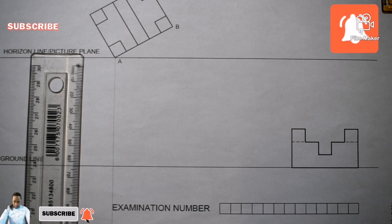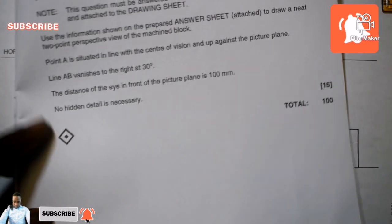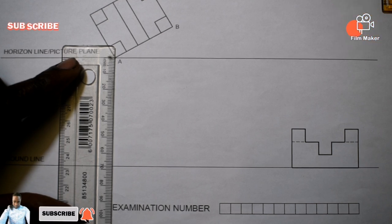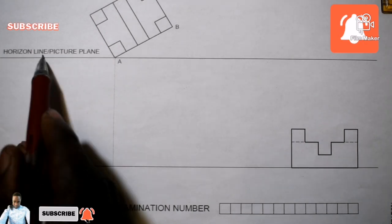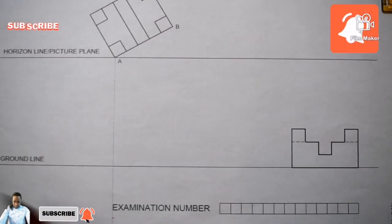The 100 millimeter that they are talking about is this one. The distance of the eye in front of the picture plane is 100 millimeter. You understand? So from point A, I go down 100 millimeter. Most of the time, the horizontal line is 20 millimeter from here, maybe 20 millimeter. That's when you get HL, which is your horizontal line.